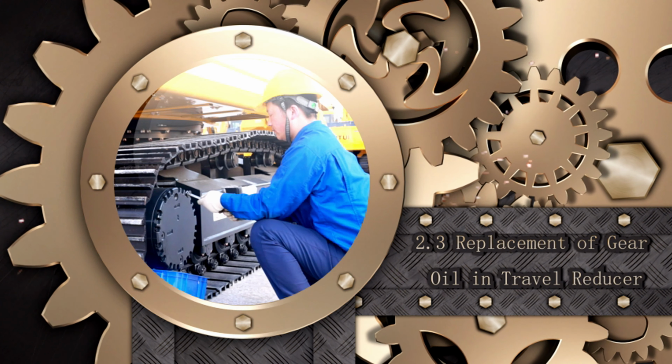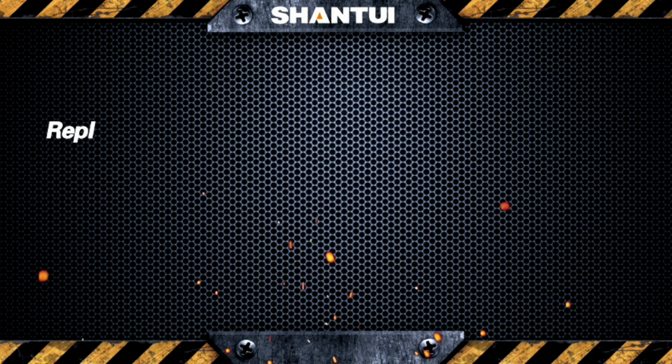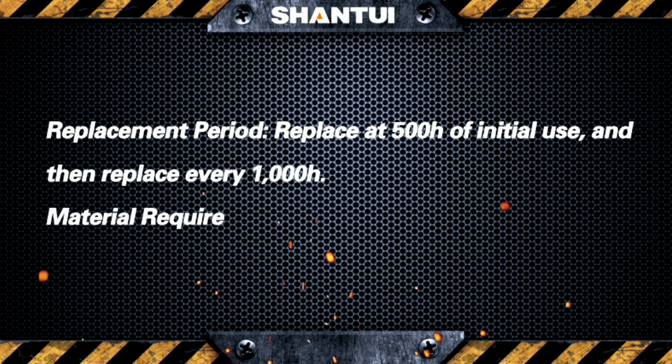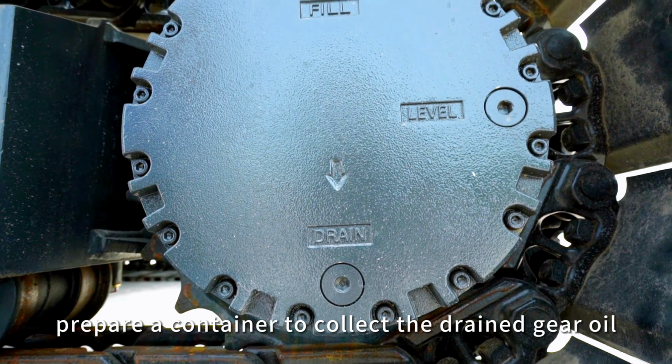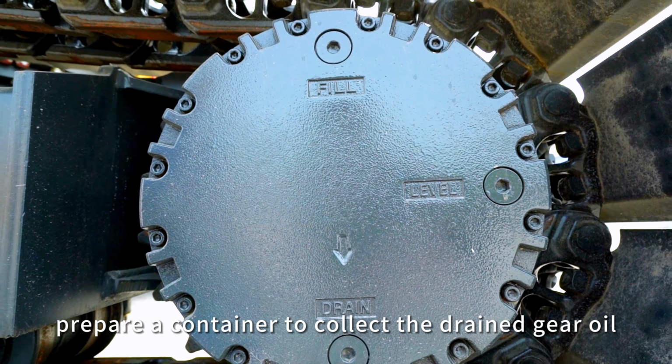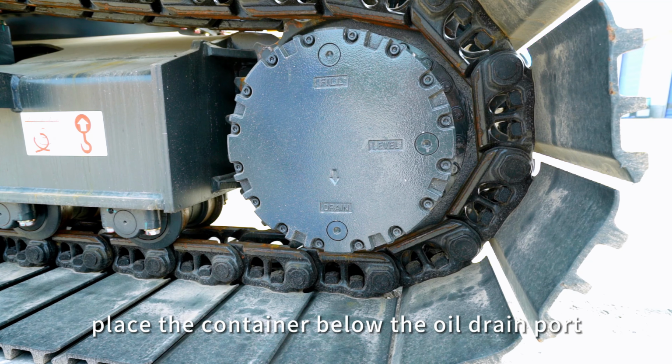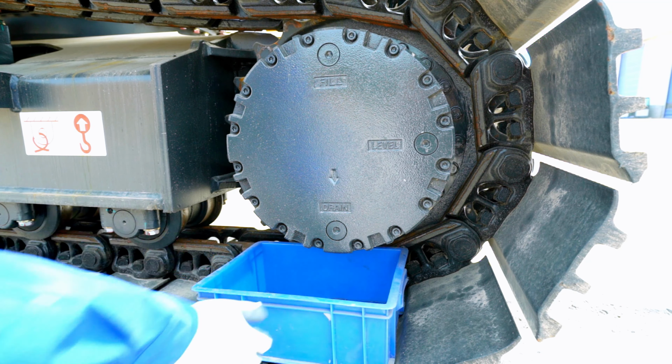Replacement of gear oil in travel reducer. Replacement period: replace at 500 H of initial use, and then replace every 1,000 H. Material required: gear oil, 11L. Steps: prepare a container to collect the drained gear oil. Make the oil level detection port, oil drain port, and oil injection port vertical to the ground. Place the container below the oil drain port.